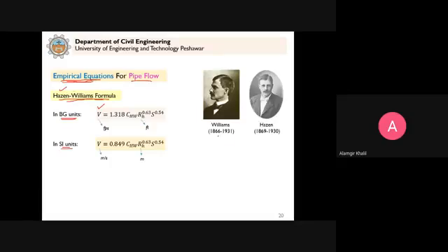They conducted a lot of research on pipe flows, and then they developed tables to calculate this coefficient here. You see, RH is the hydraulic radius. We already know how to calculate the hydraulic radius. S is the slope, HL by L. Clear? So the head loss divided by L is your S, the energy gradient. And velocity we want to calculate.